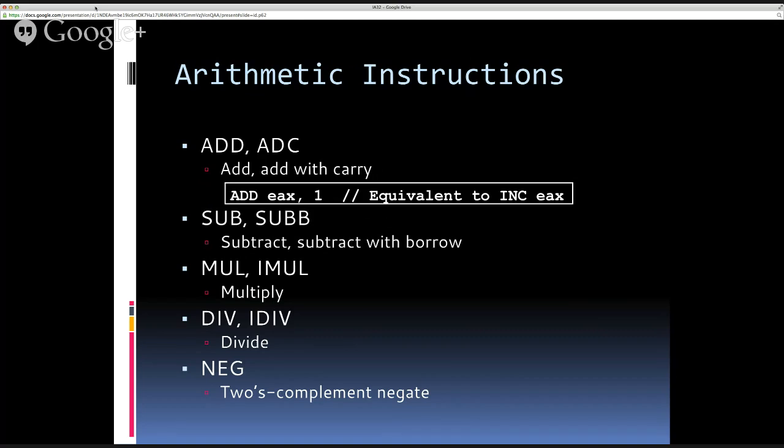And that's typically going to come into play when there are some operations and then some conditional execution statements. You need to be familiar with what flags may be set. So add, for example, the overflow flag could definitely be set as an example.